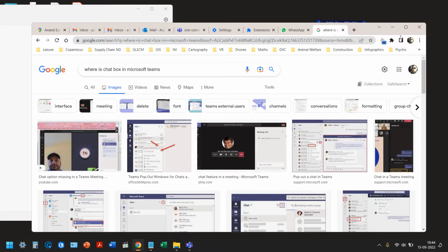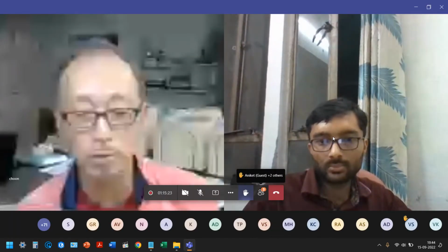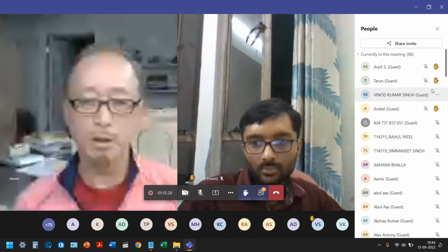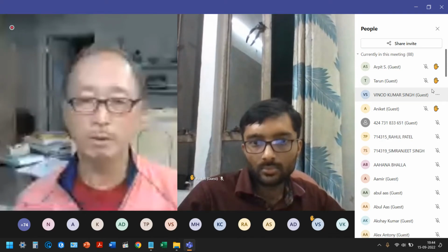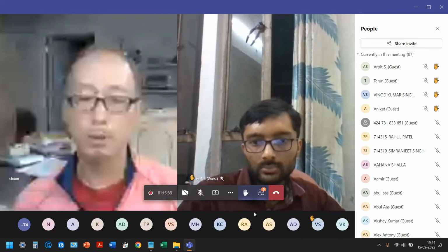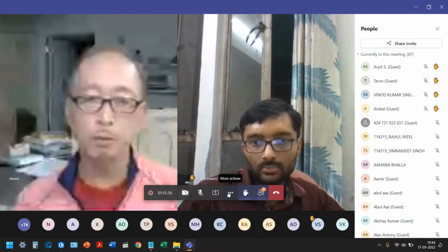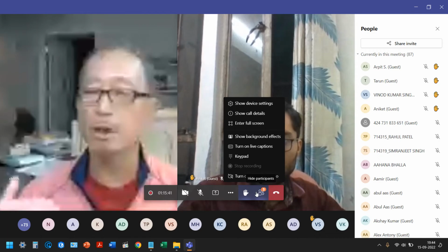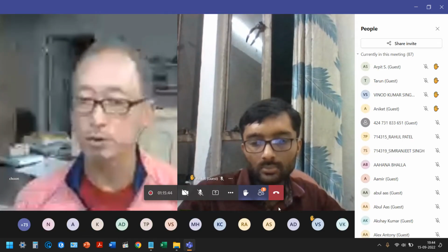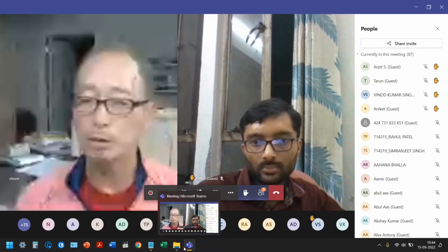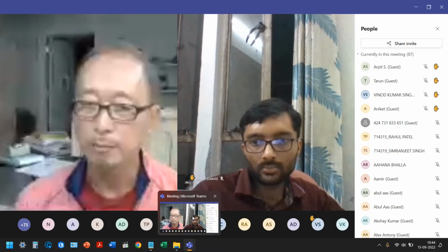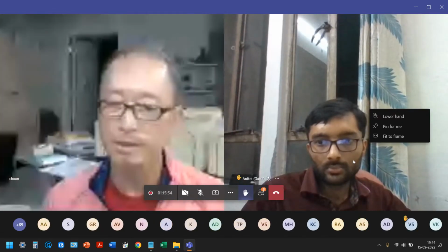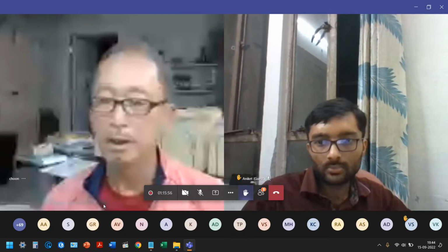So the first one: which type of geophone is good for the MASW technique? It should be a vertical geophone. As I said earlier, we are dealing with Rayleigh-type surface waves, although we can deal with Love waves. To deal with Rayleigh-type surface waves, you have to use a vertical geophone. To deal with Love waves, you have to use a horizontal geophone. But the reason why I don't usually recommend measuring Love waves is that generating and recording Love waves is a lot more difficult than Rayleigh waves.